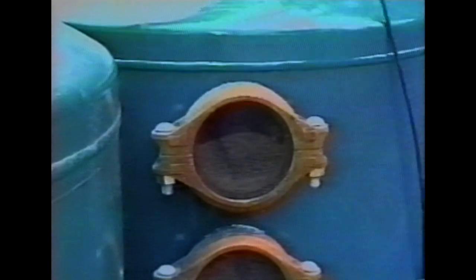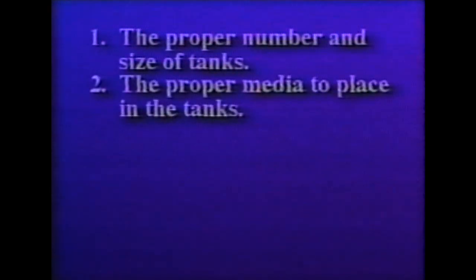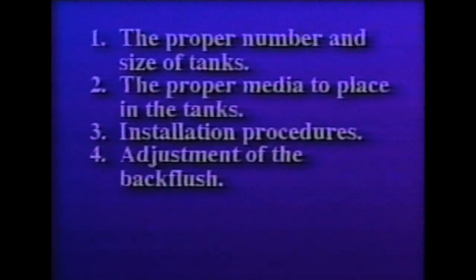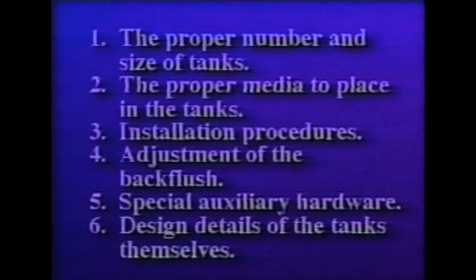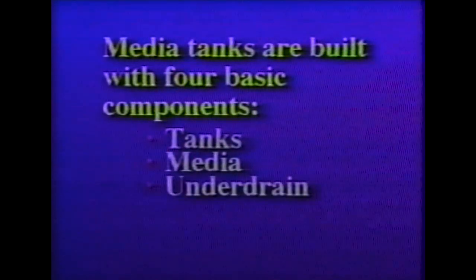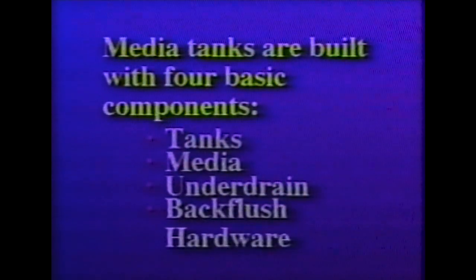In order to get the full benefit of media tank filtration, one must pay attention to the proper number and size of tanks, the proper media to place in tanks, installation procedures, adjustment of the backflush, special auxiliary hardware, and design details of the tanks themselves. Media tanks are designed with four basic components: the tanks, the media, the underdrain, and the backflush hardware.